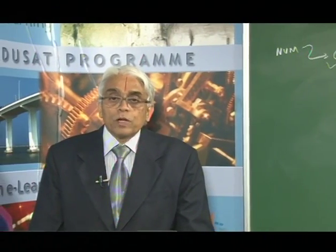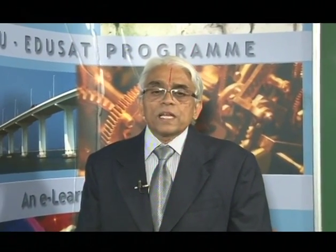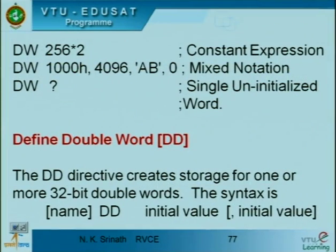Now let us look into define double word, because this is hardly used unless you are talking about division of 32 bits by 16 bits. So it is possible to access 16 bits of data and directly store it into the memory location. There are certain instructions which you will study as you go further, stating that you can move 32 bits of data from the memory location and store it into two different registers by a single instruction. Let me not discuss the instruction set now, we will talk about the assembler directives.